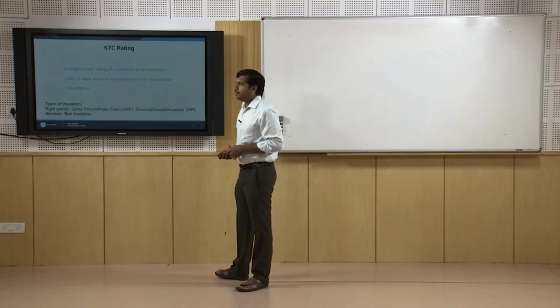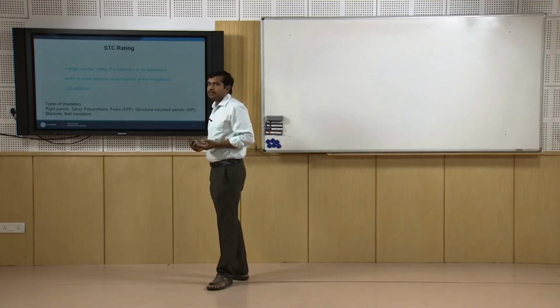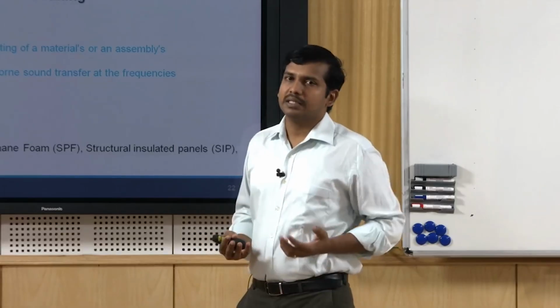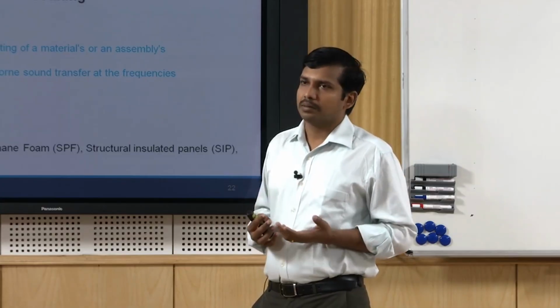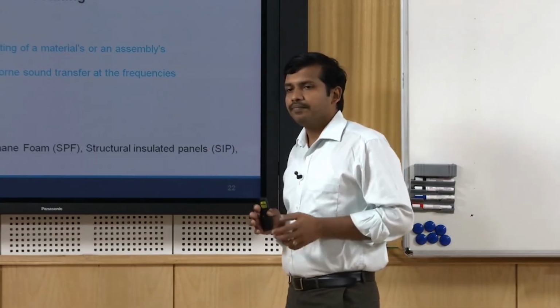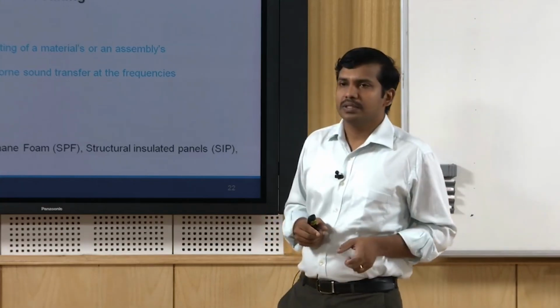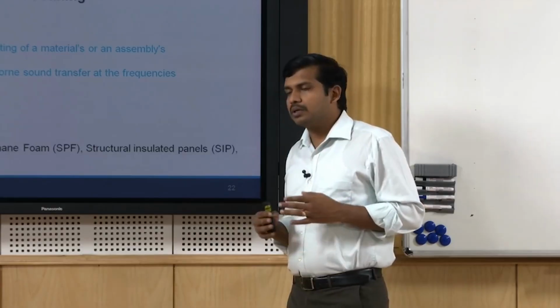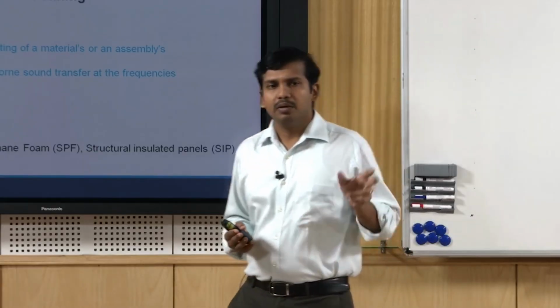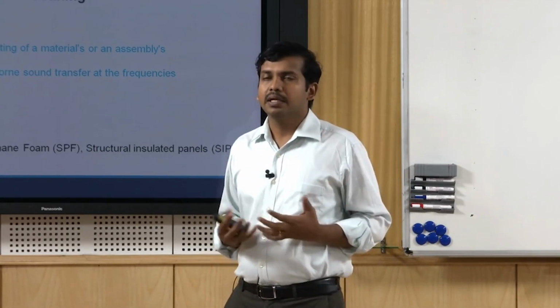Now so far we have been looking at acoustic absorption. Inside a hall you need a reverberation time, a specific signal to noise ratio and acoustic absorption. For this you were using the factor called noise reduction coefficient and alpha, the absorption coefficient. Now let us talk about sound insulation. 2 things we are talking about. First was acoustic absorption inside a room.